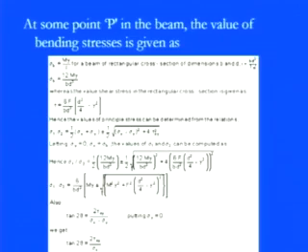So now we would like to conclude this chapter. We discussed the important phenomenon that shearing stress is very sensitive to the cross section we are using, whether rectangular, I section, or circular, and how the distribution behaves. Generally you found that the distribution is parabolic and has its maximum value at the neutral axis only. As far as applications are concerned, if you want to use any beam, we have to think about what kind of applications there are and how the bending as well as the shear stresses occur.